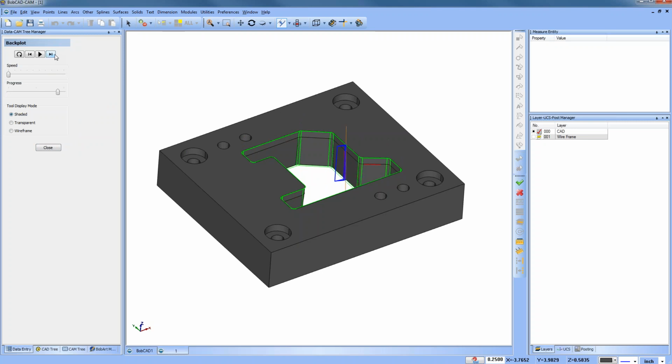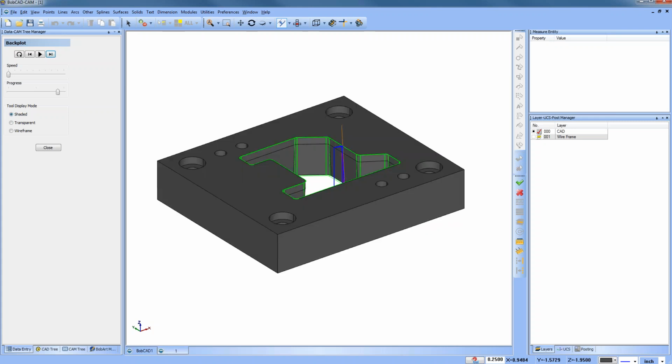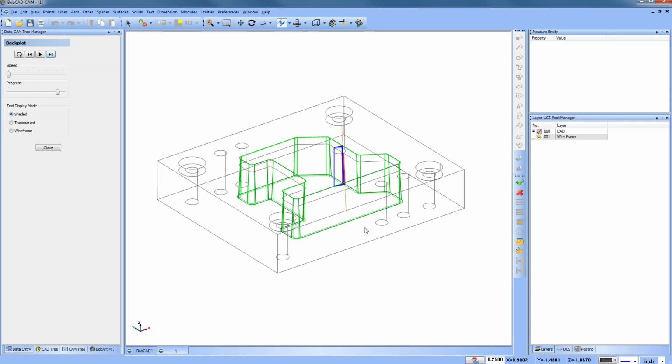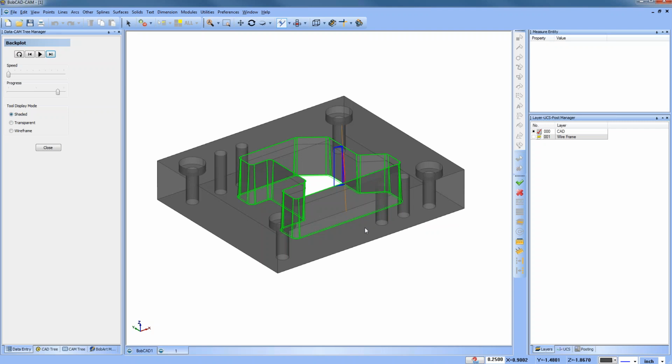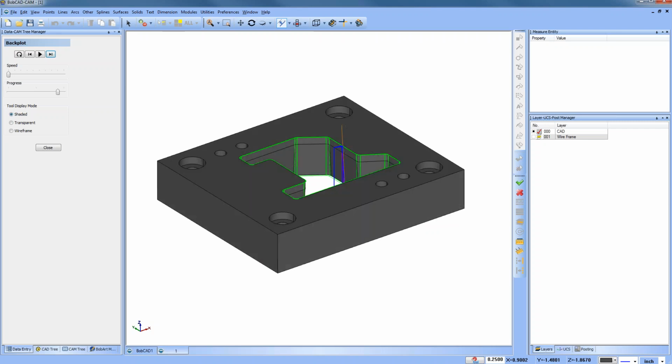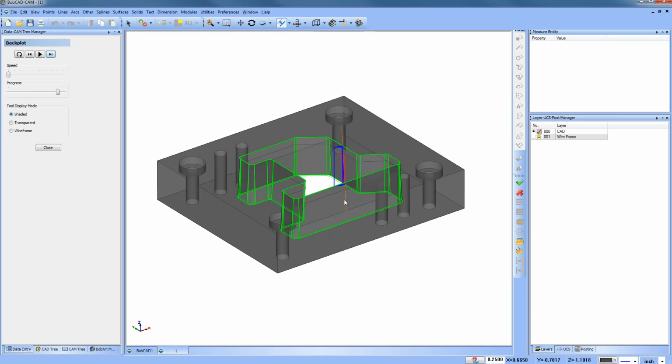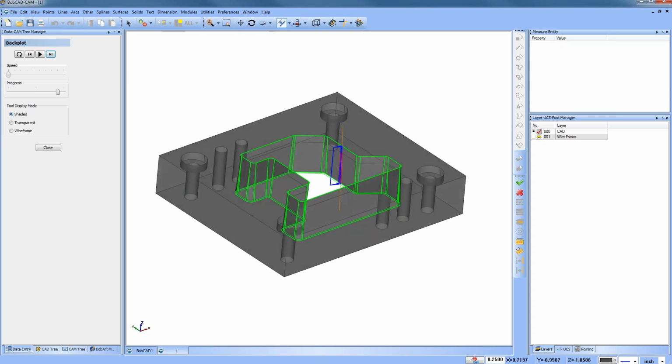All right, so a couple of hotkeys. S for shading. If you click S on your keyboard for shading, that will turn the shading on or off. If you hit T, as in Tom or transparent, on your keyboard, that will show you the transparent view. If you press your center mouse wheel, that will get you to a rotate.